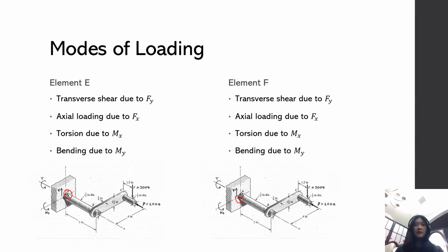Then it was time to determine the modes of loading at each individual element. First, looking at element E, there's a transverse shear force due to F of y, there is an axial loading force due to F of x, and there's a torsion force due to the moment about the x-axis. There's also a bending force experienced at element E due to the moment about the y-axis.